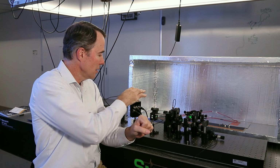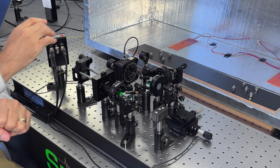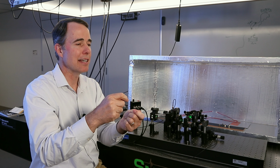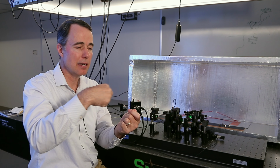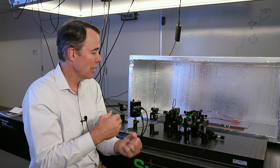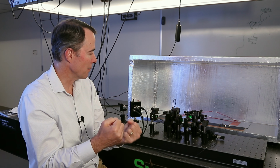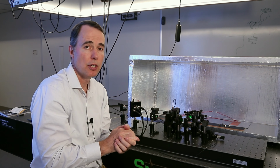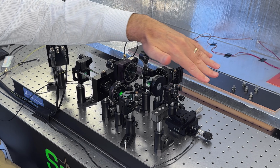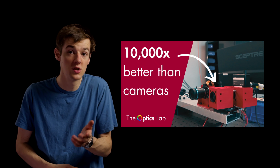Then inside of this device, it takes the difference between those two powers, and then it sends out an amplified signal that amplifies that difference between the two, that we can then measure and be able to back out how much the frequency changed or how much this piezoelectric moved. It counts the number of photons on one side and the other and takes the difference between the two. If you want to know how else we use balanced detectors, check out our triangulation video, which is linked at the end of this one.